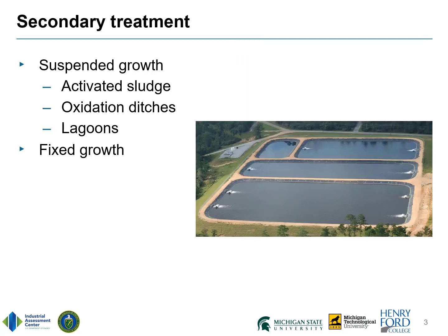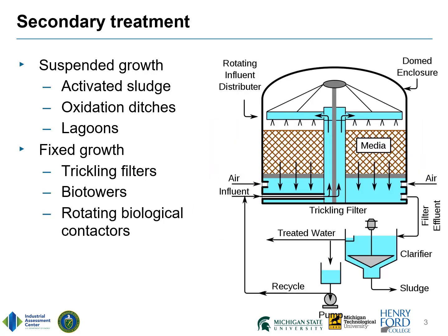Lagoons are low-technology pond-like bodies of water. Mechanical aeration may be used in aerobic lagoons to ensure sufficient oxygen levels in the water. With trickling filters, the water is distributed over a bed of rocks or plastic media to which the microorganisms are attached. Typically, a rotating nozzle distributor is used to spray wastewater over the surface of the bed. Biotowers are similar to trickling filters.